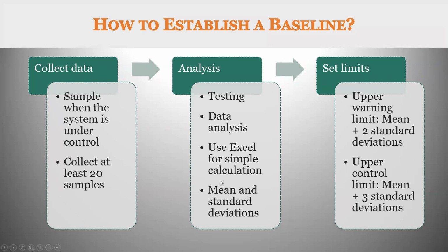Thank you, Morgan. You have discussed the sampling techniques and when and where and how often to sample and what to test. Now I would like to discuss how to establish baseline. For some people, they decide not to establish baseline, but I would argue that having a baseline can really help you to evaluate your sanitation performance. It is not really a difficult task. It's actually rather simple. The process will involve 3 steps. First is collect data, second is analysis, and third is set limit.